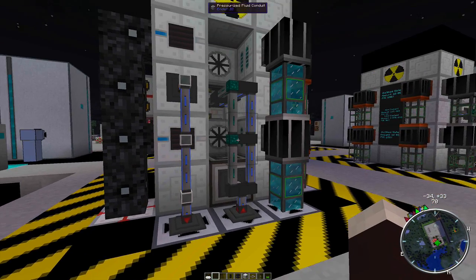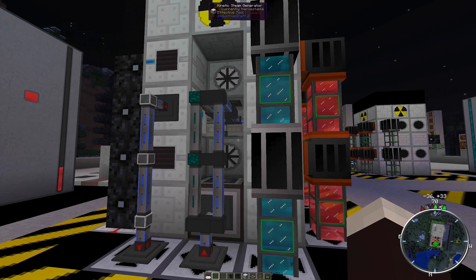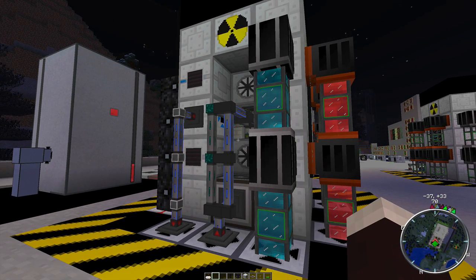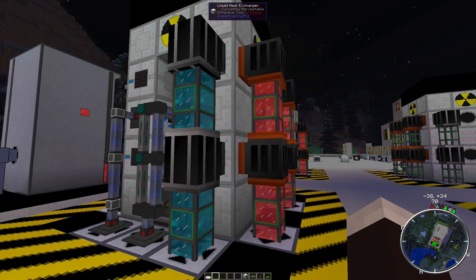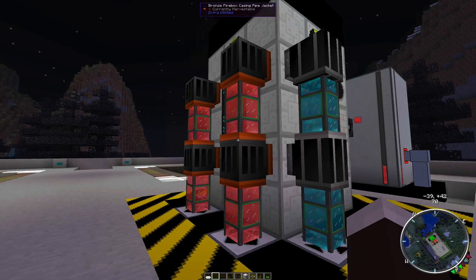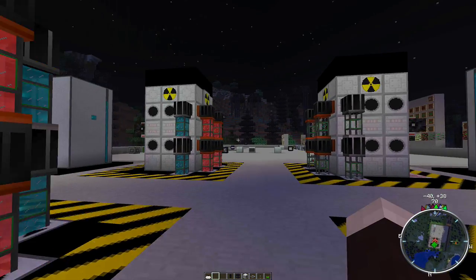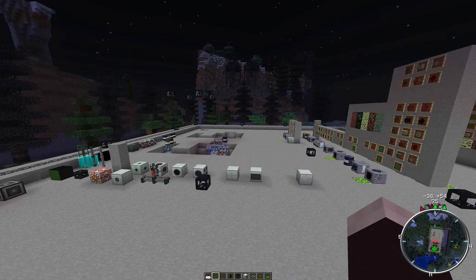It takes distilled water as well. That's what goes in the boiler. And you can use regular water, but if you do, it's going to calcify inside, and then you're going to have to tear it down and put a new one in there. And we don't want that. So we're using distilled water. So let's get started building this bad boy.